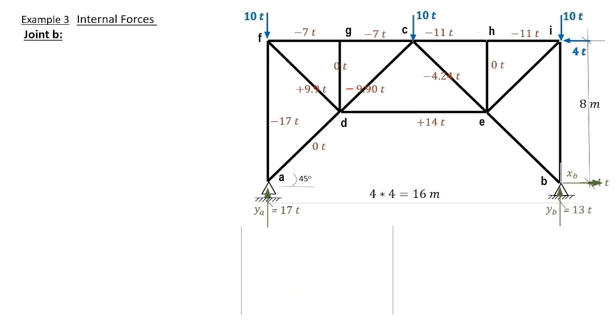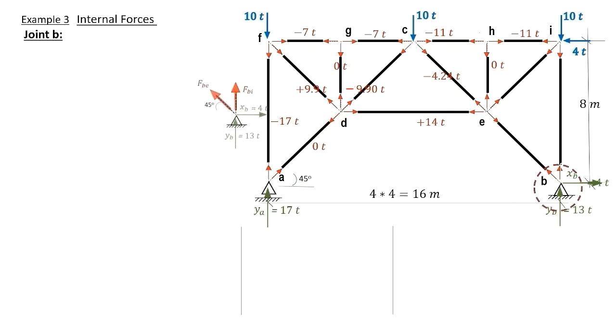Now we consider joint B. We extract it here, having the external forces, reactions YB and XB, and the internal forces FBI and FBE.